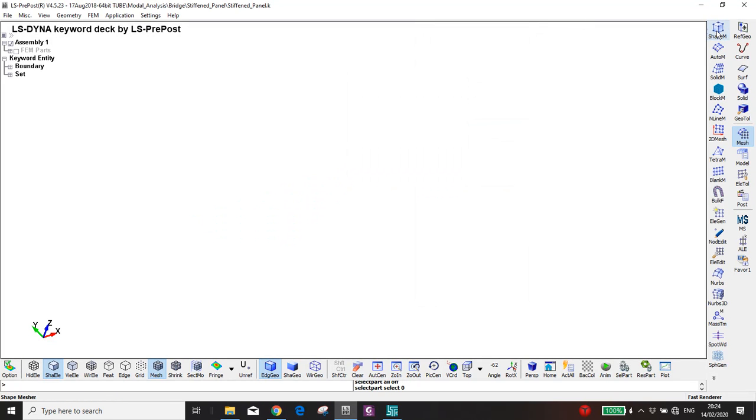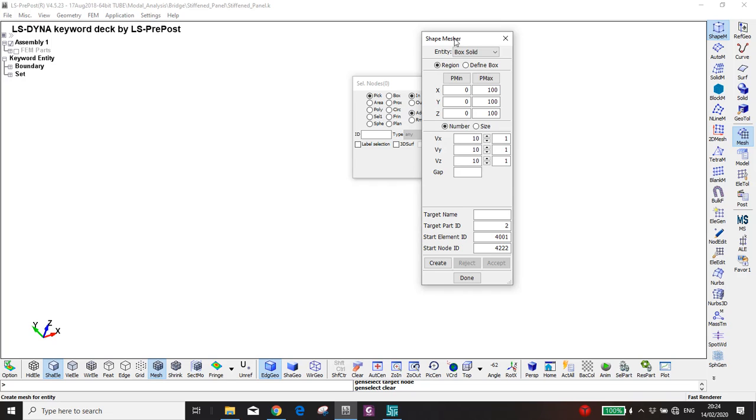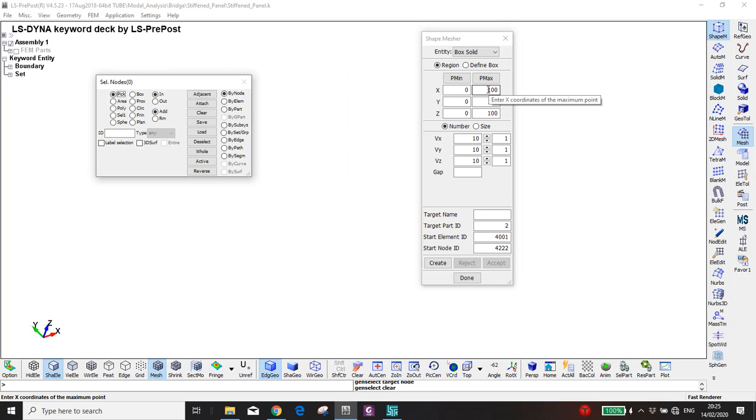Now since we say we're gonna make it as solid elements, so here in the y direction is 14, and in the, sorry, in the z direction is 11, and then the x direction we make it straight away 4150. These are in millimeters, so we change it to meters. Okay, create.